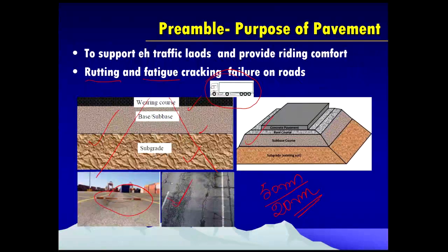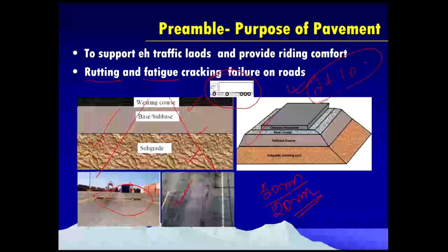Not only that, geosynthetic materials help us in extending and enhancing the life of pavements. Most field engineers say, sir, if I add geosynthetics it is going to increase my CBR from 2 to 5 or 2 to 10. This is not the correct understanding. If we use geosynthetics, a geotextile, whatever it may be, it is not going to increase your CBR. It is going to extend the life of the pavements.